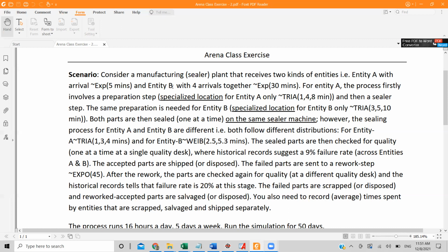In normal circumstances you say okay, thank you, and you leave. Even if you're using a queue, everybody understands that you have released the nurse, so the nurse can attend to another patient, right? Or at a cash counter you say thank you, and another one can understand that you have released the resource. But here you say seize, delay, release. When you say seize, delay, it means that you're not releasing the resource. You want to carry the resource to the next step, and then you want to release.